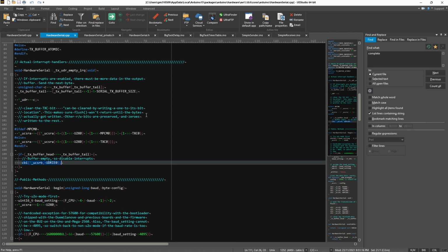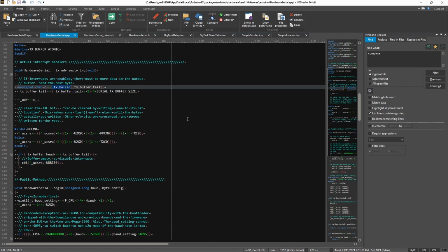And so if I get time or feel it's appropriate, I might show a routine that has a large print. It is a bit difficult to see, but you can actually see the LED start blinking again after a pause when you send a huge amount of output. And the reason that's happening is when you send a huge amount of output, you fill up this buffer very quickly. And as I said, the Serial.print blocks, meaning it has to wait until,